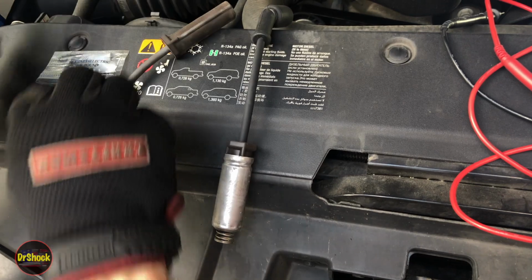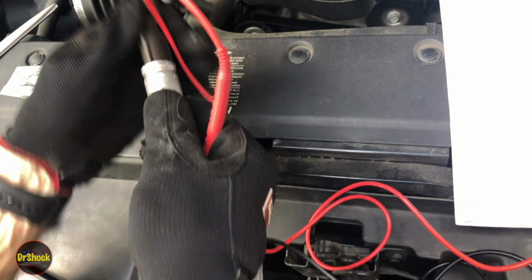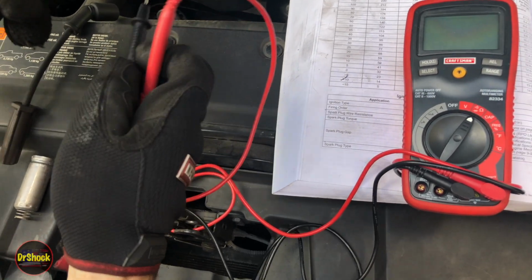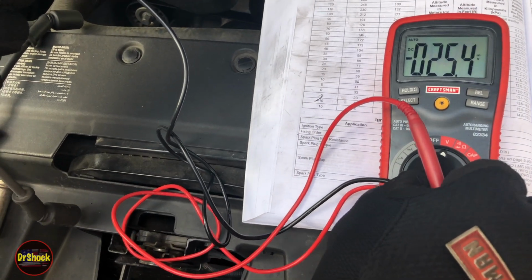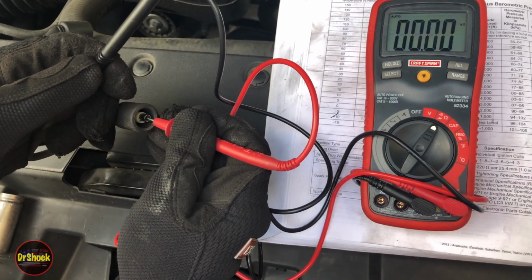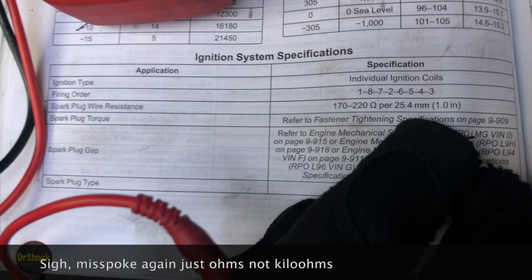Actually, you know what? Before I do this, let me show you what the resistance measurement is on a brand new one of these. Let's slide this guy off again just so we can make sure we're getting good contact. So we said before that this old one, let's cycle this guy back on because he auto timed off. This old one we were getting 402 kilo ohms, and we said that we're supposed to get in this range per inch.